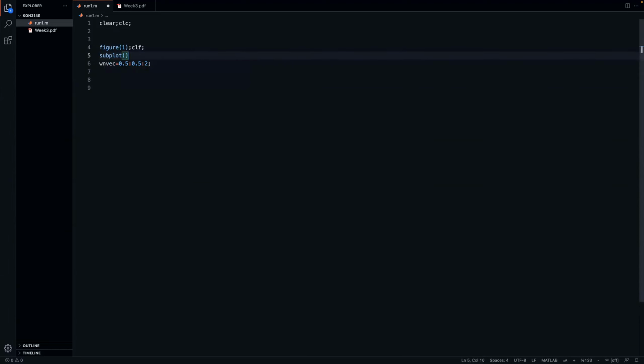Let's have a subplot where we basically plot one row. Let's have 3 columns. The first of that, CLA, hold on, grid on. Let's have X label time. So this is going to be the impulse response of the system. So Y label is going to be the output of the system. In this case, let's call the title the impulse response.